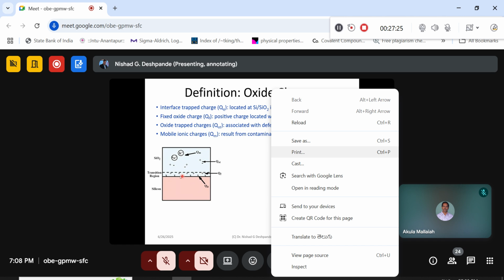See, what is happening is at the interface or these surfaces, the charges are getting accumulated, so naturally they produce some capacitance over the whole region. If I can calculate the capacitance of the whole region, naturally I can get a very good gradient along the thickness with respect to the voltage, and one can understand all these trap charges.